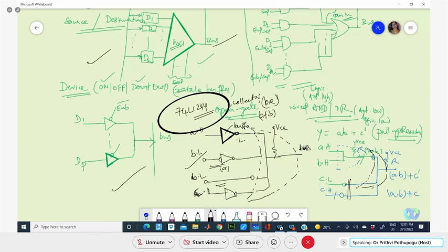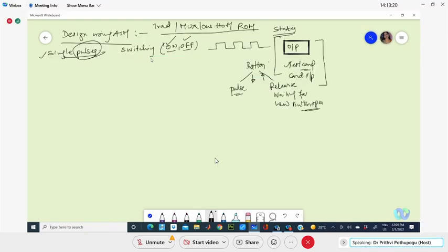Release the button, and only for a new pressure applied, a new iteration of applying pressure on the button, the second pulse or the next pulse will come out. So for a pressure applied, it should be only one single pulse.